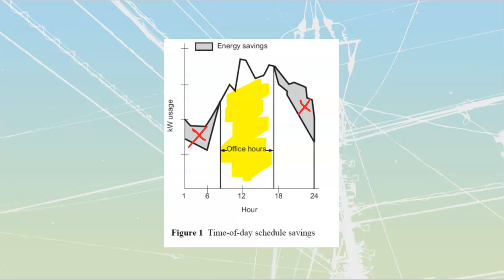I'm not going to go over the top of the settings inside there. The standard for those is going to be 21 degrees as our indoor standard. That's what you've all become accustomed to over the years inside of schools and inside of your houses, that 21 degrees. And so we, as North American humans, feel accustomed to that. Different societies have different indoor air temperatures that they set them to. Different parts of the world will set these things to different ones based upon what is deemed as comfortable, and people just kind of adapt. So if you are going to set anything up for a customer, 21 degrees target temperature.